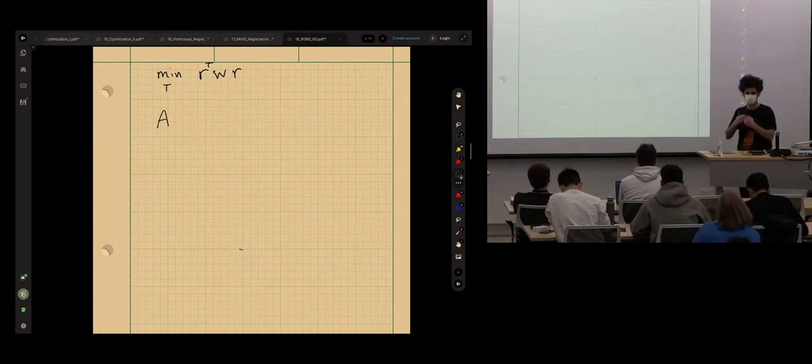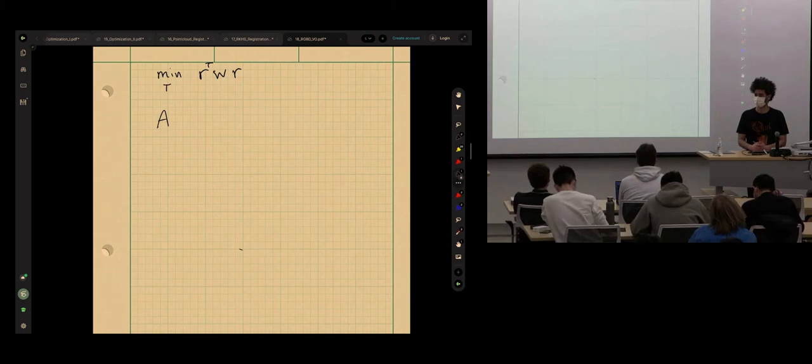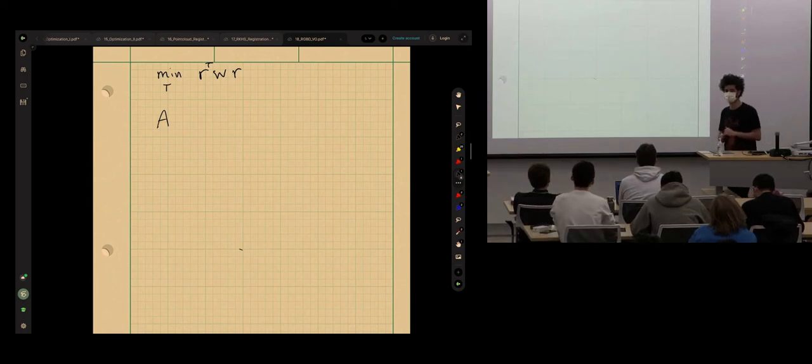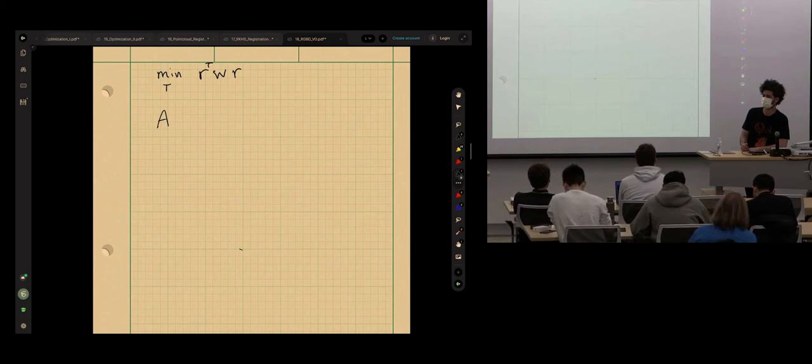We integrate it using the exponential map. Twist has 6 dimensions. And the loss function, the residual in this case, is actually scalar. It could be a vector in least squares, but here it's just intensity. So the Jacobian is 1 by 6, right? Okay. So it's a mapping from the variable to the residual, whatever is the space of the residual.